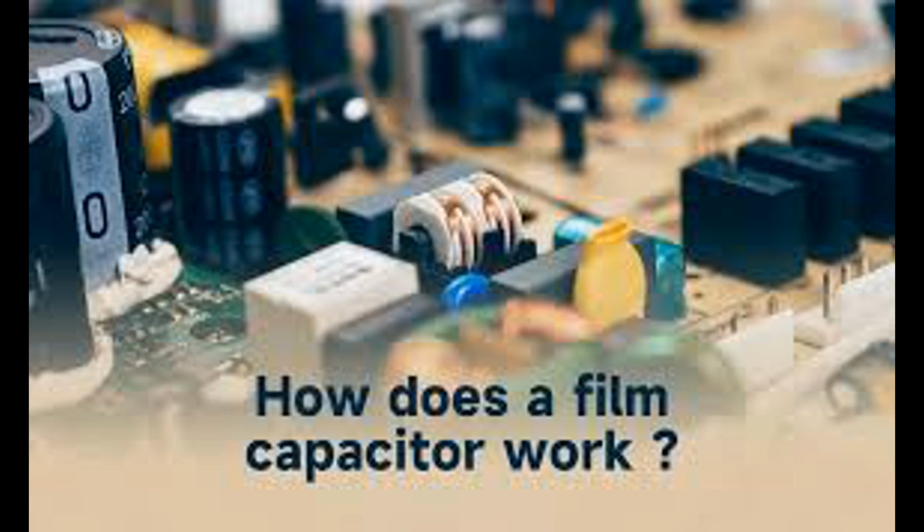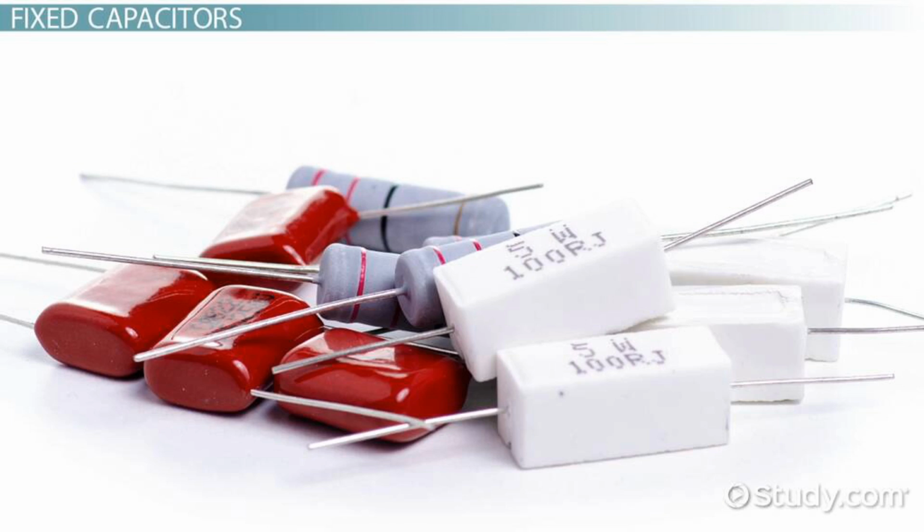Moisture resistance, reliable in harsh environments. No drying out, unlike electrolytic capacitors, ensuring longevity. High dielectric strength, supporting high voltage applications. These advantages make film capacitors one of the most reliable and versatile components in electronics, offering long-term performance in applications ranging from consumer electronics to industrial power systems.